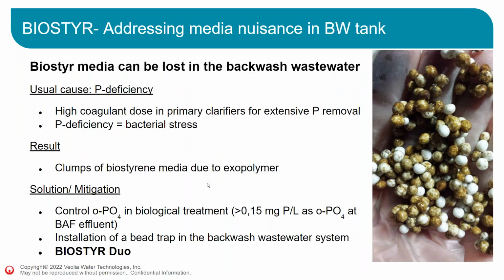So Biostyr. You might have heard that some people are concerned about losing some media during backwashes into the backwash tanks, and getting the beads out of the backwash tanks is not an easy task. Most of the time, this is due to bacterial stress. What could cause bacterial stress? One of the causes we've seen often is the lack of phosphorus. There's not enough phosphorus in the Biostyr. The result is that the bacteria are stressed. They create exopolymers, and these exopolymers create clumps of Biostyrene beads that will be dragged through the backwash.